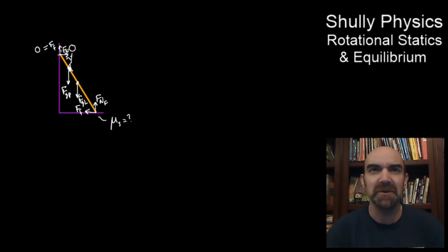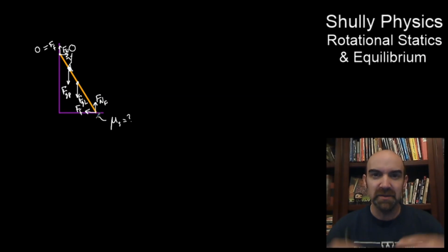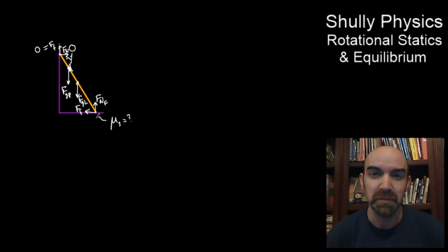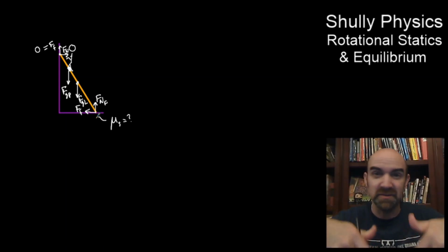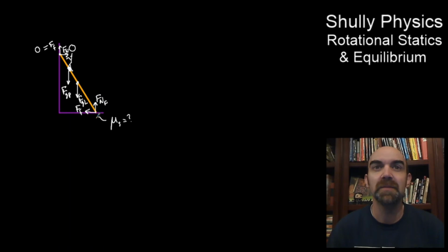So we're not going to rely on friction from the wall at all to keep this system from moving. That means it's only the friction, the mu from between the ladder and the bottom, that's going to be important here. And that's generally what ladder manufacturers will focus on. They're not going to be counting on friction on the wall to keep this thing from sliding. Oftentimes they'll put these feet at the bottom that either dig in really well, if this is an aluminum ladder that goes really high. Make these adjustable feet that either have rubber pads or they can be rotated so they have these claws that dig into like a soft soil, ground type of thing. So we're going to say 0 friction at the top.